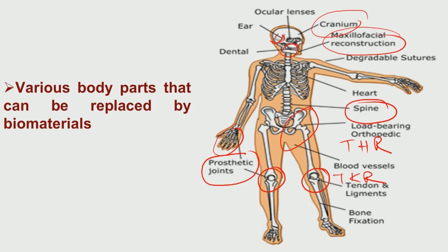And titanium 6% aluminum 4% vanadium which is used as dental implants, we are currently investigating how one can put a hydroxyapatite coating to provide this kind of implant better osseointegration. At the same time, one can also put on the abutment part a diamond-like carbon coating to reduce the frictional properties of this implant material.